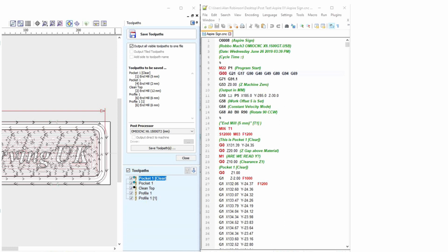The D word is optional. If there is no D word, the radius of the tool currently in the spindle will be used. If used, the D number should normally be the slot number of the tool in the spindle, although this is not required. It is okay for the D number to be 0, a radius value of 0 will be used. G41 and G42 can be qualified by a P word. This will override the value of the diameter of the tool, if any, given in the current tool table entry.